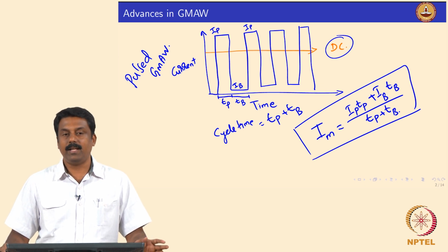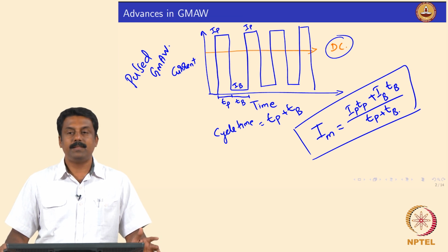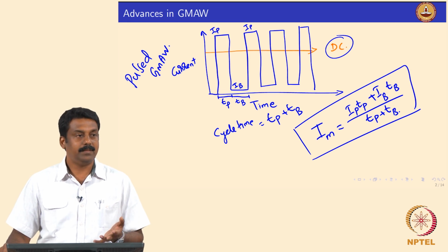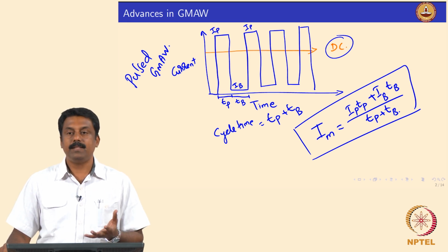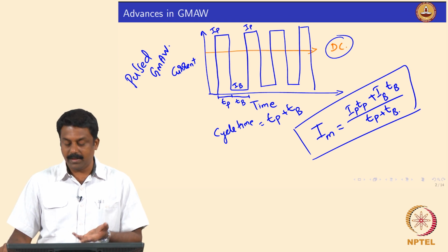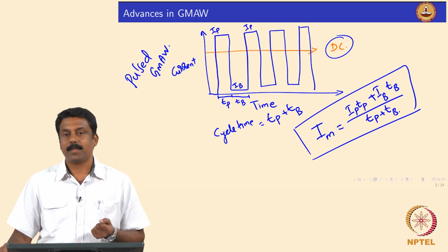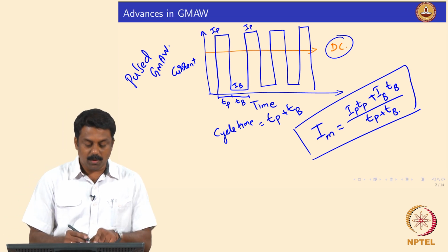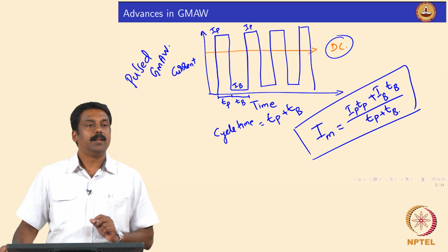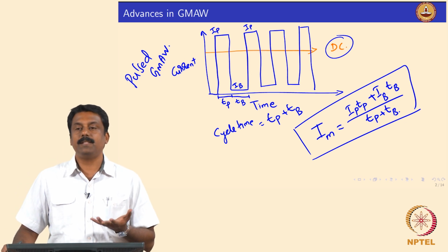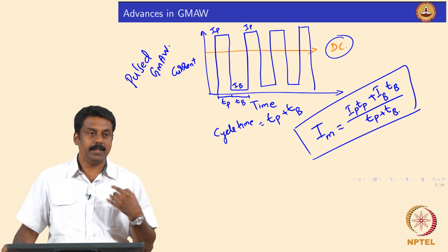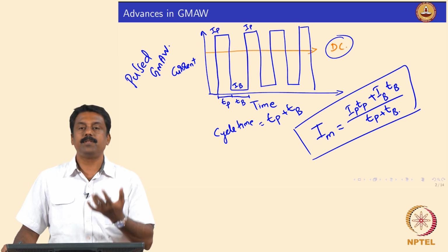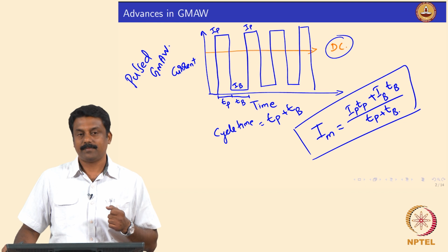So, the other advantage here is that you minimize the damage you do to the base material because you are reducing the heat input or arc energy significantly without compromising the transfer characteristics that you achieve otherwise with a constant current, right. And by carefully controlling the power source characteristics we can achieve one drop per pulse. So, by carefully selecting the pulsing frequency, we can also determine how many droplets you want to detach per second, isn't it.